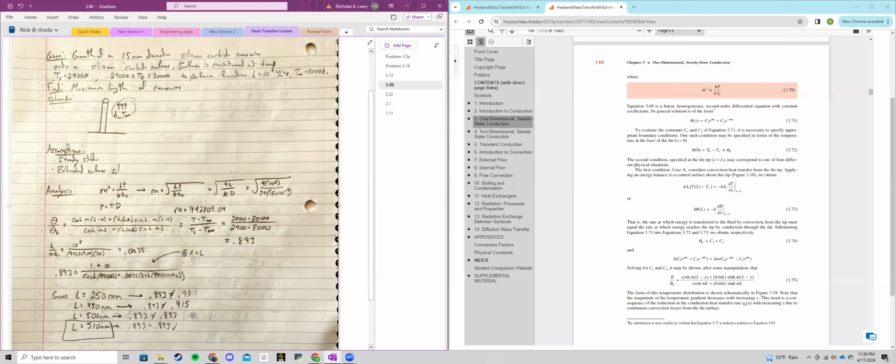Guess and check is used for a couple of different heat transfer problems. It's just a type of solution when you have complex functions that require solutions of your variable, which are in deeper issues, like the issue here where that L is embedded in the hyperbolic cosine and hyperbolic sine. Casual geometry or algebra would probably take a really long time to get the L out of that function in order to actually solve for it. So guess and check is the way to go on this one.